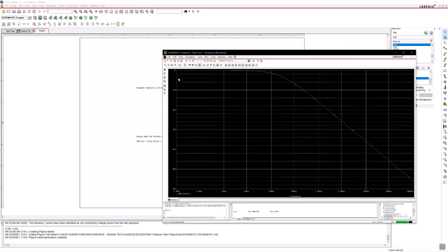So 0 decibels means that the output's equal to the input. Then minus 10 and then minus 20 means that we're not getting as much of the input on the output. So that means here, for instance, minus 30 decibels, that means we're not getting very much of the input signal on the output. In other words, we're filtering it off.